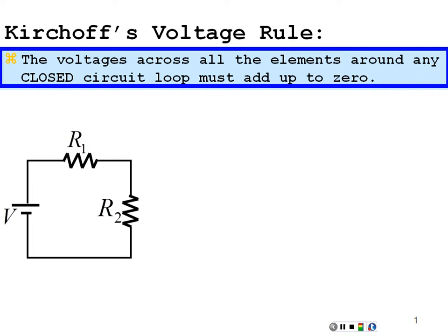And so in a circuit, if you start at a certain potential, which is the height within your electric field, and come back to that potential, your total change in potential will be 0. So we're going to use this as the central key to this idea of branch current analysis.